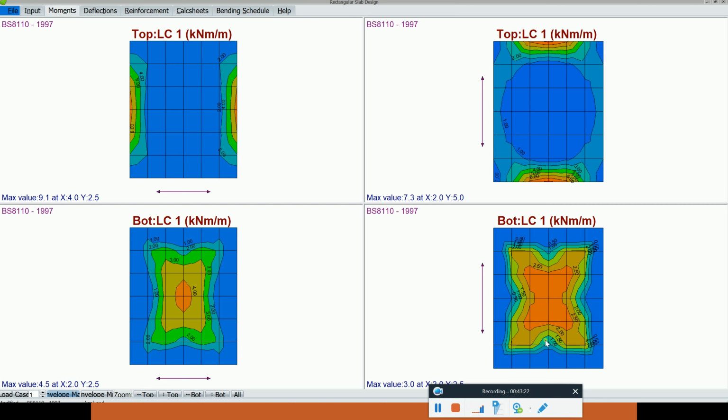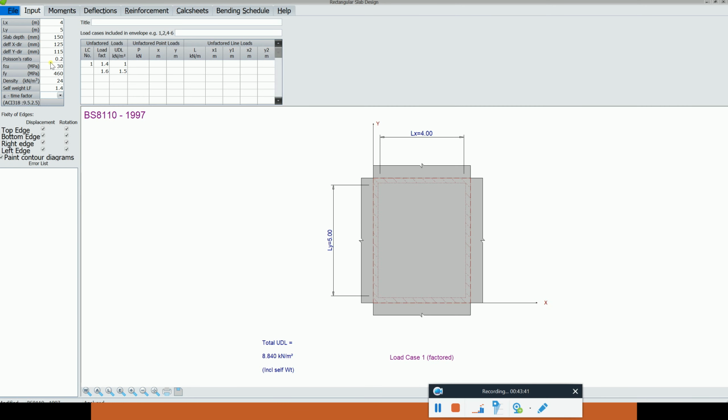The same way on the other side, we can see that once again it's continuous on this side, continuous from this side, so it's going to be having a top bending moment in both sides, and then the remaining side is going to be bottom. Now to understand a little bit, let us try to have a different approach.